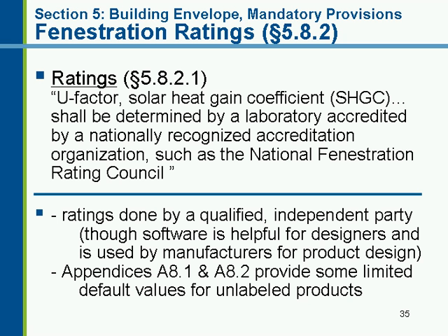In terms of the ratings, Section 5.8.2.1 indicates that they have to be determined by a laboratory accredited by a nationally recognized accreditation organization, such as the National Fenestration Rating Council. So what we're looking for here is some independence. The ratings are done by a qualified independent party, which doesn't mean that it's not good to use the software. And the software can be downloaded from NFRC websites.